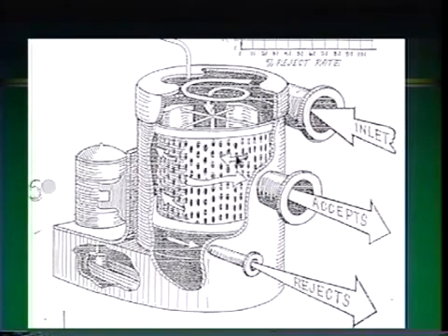And then the material that we're going to reject, and this is going to include a lot of fibers, because to get the throughput and the processing that we need, we have to reject some fibers, and we'll talk about how we save the fibers later. But the rejects actually can't pass through these holes. They fall down to the bottom, and then they pass out this rejects port.